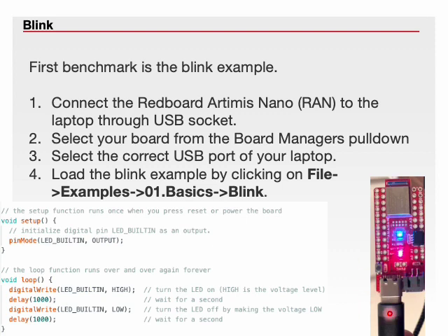Select your board from the board manager pull down. Select the correct USB port of your laptop. Load the Blink example by clicking this example from File, Examples, Basics, Blink.